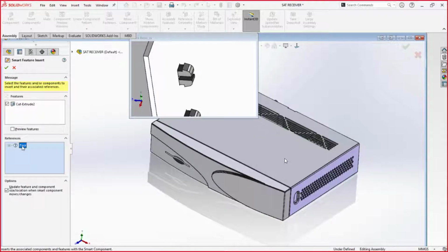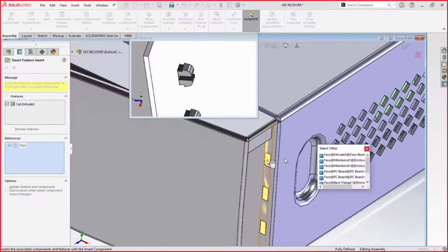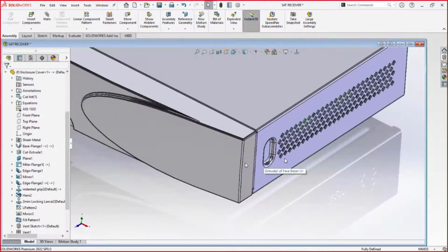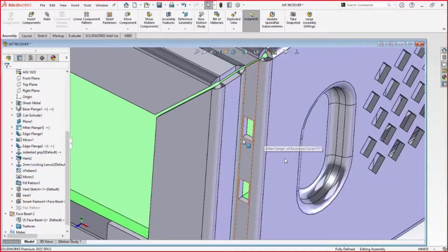So we have the advanced option that right click on the face and select order will help us to snap the faces and recognize them and again directly select them. Easiest way, right? So in other softwares, it is quite difficult to do this. So once you click on the green check, you'll have the final model like this, which has the holes automated inside.